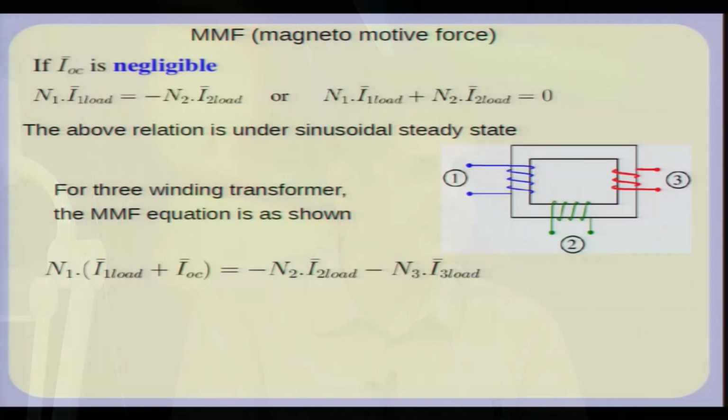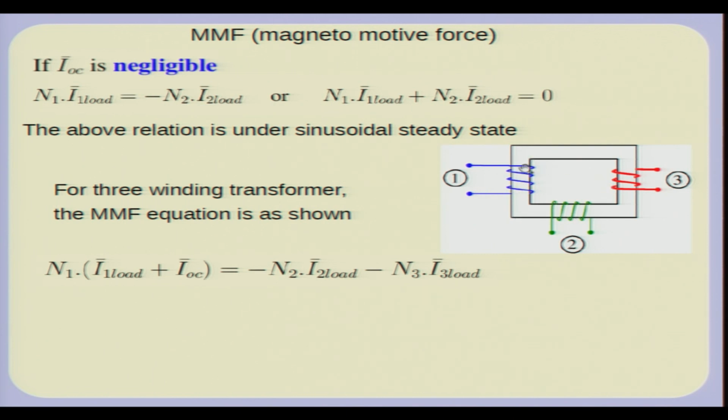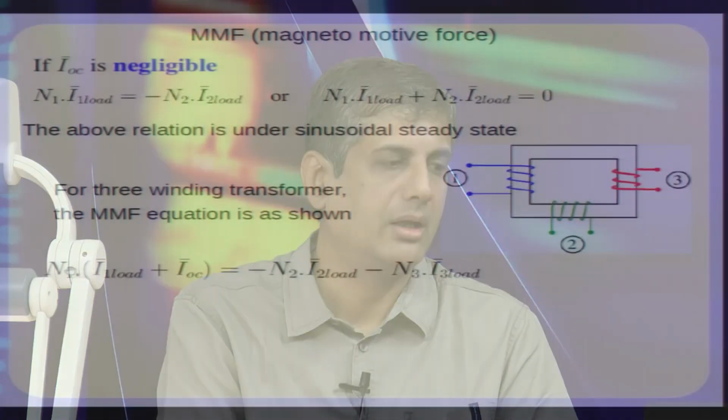Okay. Now, remember, for a 3 winding transformer, you need not be limited to 2 windings. In this 3 winding transformer, where all the currents are entering, for example, for the first winding, the current is entering this point, the current is entering this point and the current is entering this point. All the 3 windings, this will be essentially the relationship which holds. This is not very difficult to prove, only here you will have to have V1, V2, V3 and I1, I2, I3. The relationship will now of course be mediated with a 3 by 3 inductance matrix, and you can actually prove V1 is to V2 is to V3 will in fact be N1 is to N2 is to N3. And using these relationships, one can in fact find out that this is in fact true.